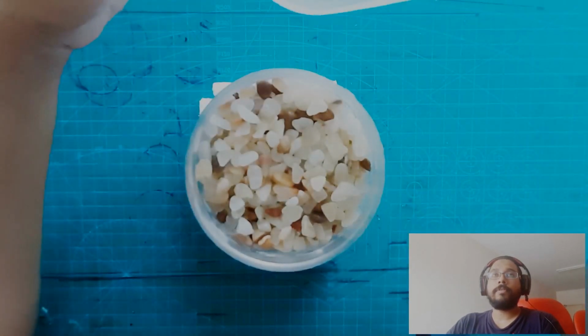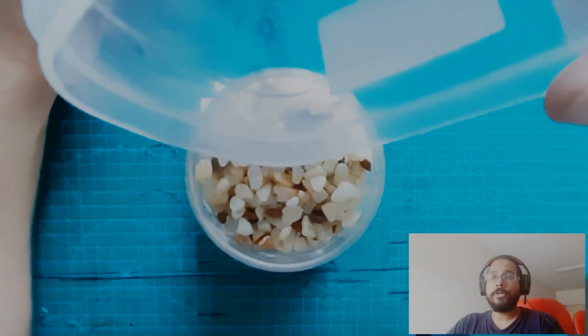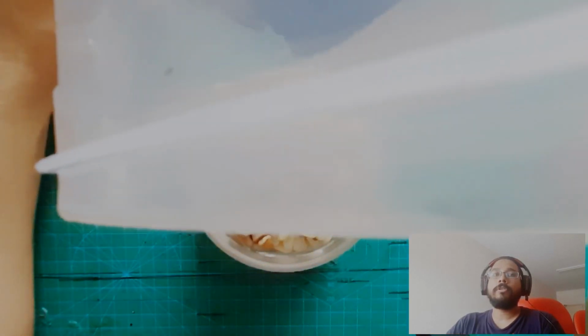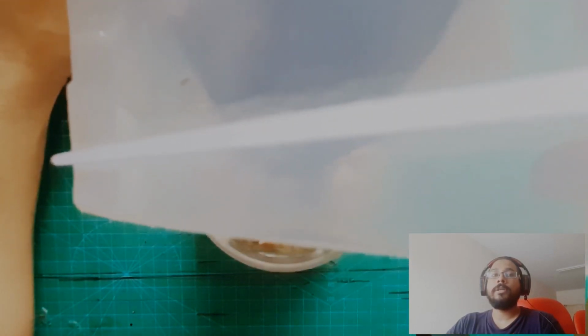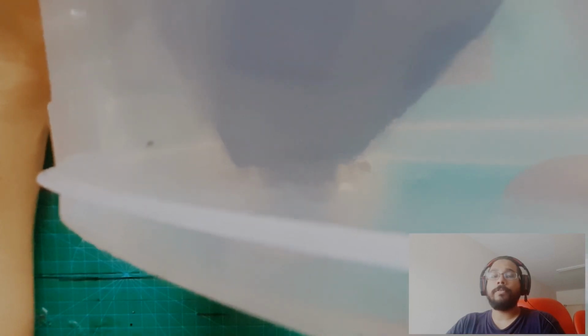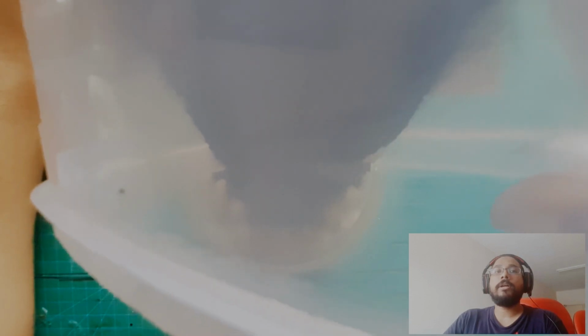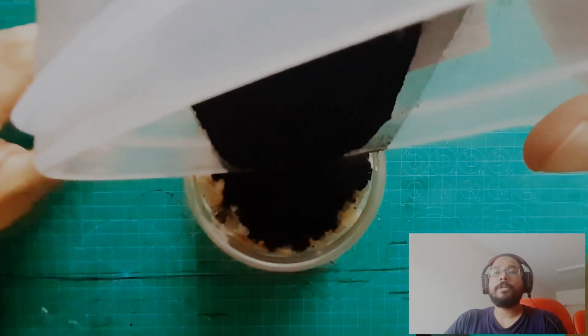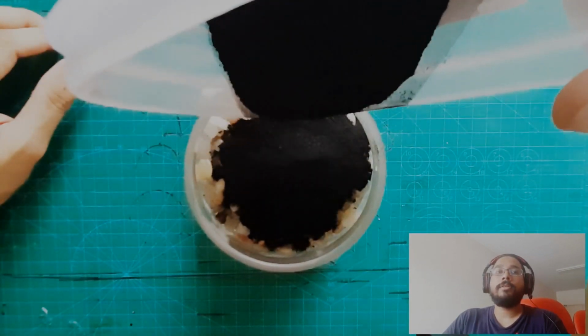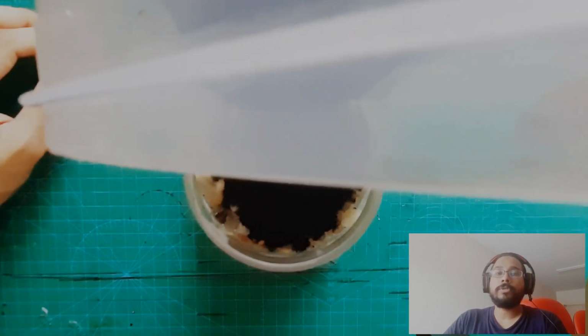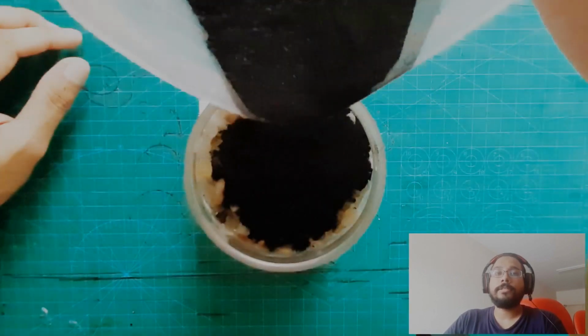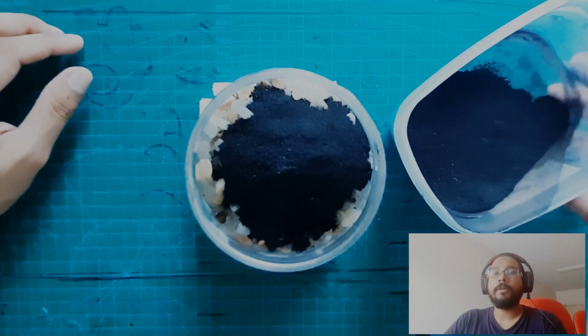Another factor that could have affected the results is using powdered charcoal. The powdered charcoal added even more finer particles that was not properly removed by the filter. This may again have contributed to increase in turbidity and also made the treated water slightly more acidic along with the excess alum already present. This can be observed in the results obtained. The solution for this could be to use granulated charcoal instead of powdered charcoal, so that it can still filter the water without increasing the turbidity.